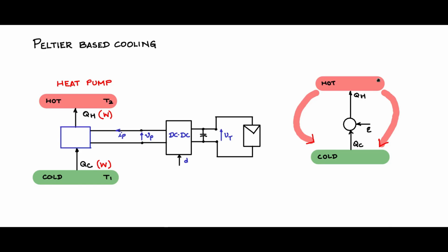So it becomes very, very important that not only do you have to pump the heat up, you should retain that heat there or remove it elsewhere so that it doesn't come back to the cold junction and reduce the delta T. It is analogous to water pumping.